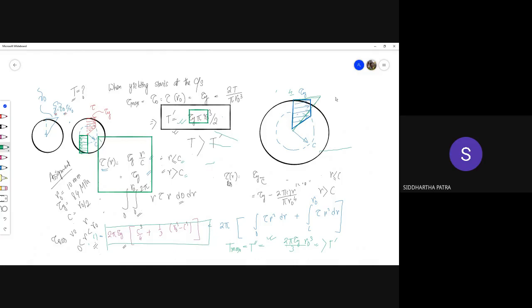So if that torque could be applied without crossing the elastic limit. Because in unloading you have this twice tau y window of elasticity. So you can do that actually. So this is the stress that needs to be recovered.